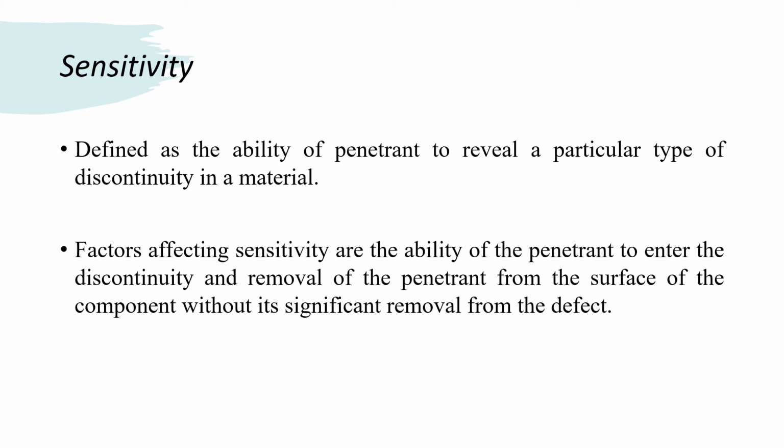This is related to fine or wide discontinuities which are deep or shallow in nature. Factors affecting sensitivity are the ability of the penetrant to enter the discontinuity and removal of the penetrant from the surface of the component without its significant removal from the defect.